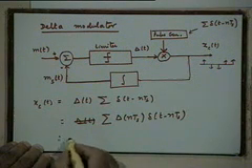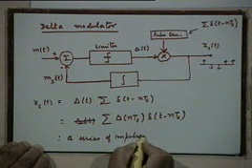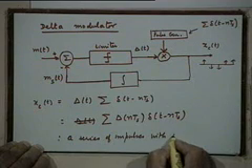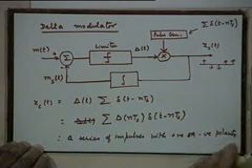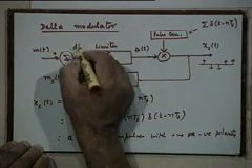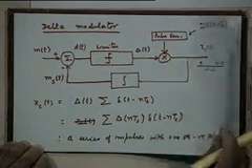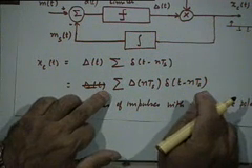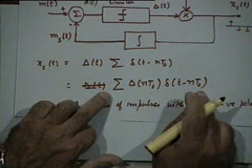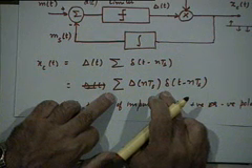So this x sub c(t) is essentially a series of impulses with positive or negative polarity, depending on the sign of this difference signal. If I call this difference signal d(t), δ(t) is a quantized version of d(t), right? Now let's look at the reference signal. The reference signal is being generated from this signal, isn't it? How? By integrating this. When I integrate this kind of signal, what will you get? This impulse will become a step function, right?